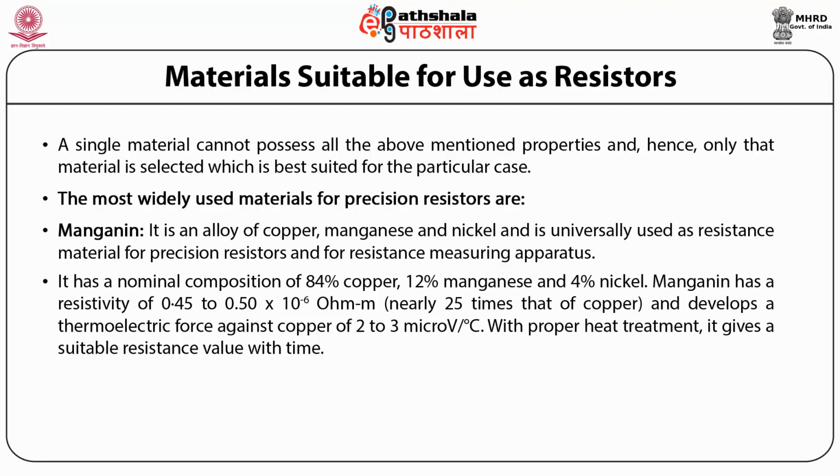Manganin has a resistivity of 0.45 to 0.50 multiplied by 10 raised to minus 6 ohm meter, which is nearly 25 times that of copper. It also develops a thermoelectric force against copper of 2 to 3 microvolt per degree Celsius. With proper heat treatment, it gives a suitable resistance value